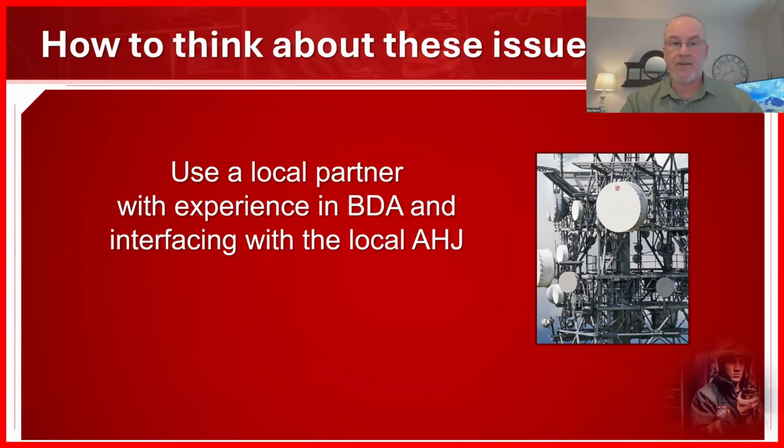They can say, okay, you're going to need this test. This AHJ is going to require this. They're going to require conduit here. They're going to require this rating. Okay, so these are the things you need to include as you're trying to budget this, because there's really going to be no other way for you to know that unless you're dealing yourself with the AHJs every day on this kind of thing.